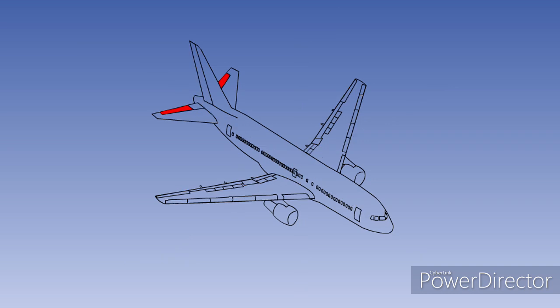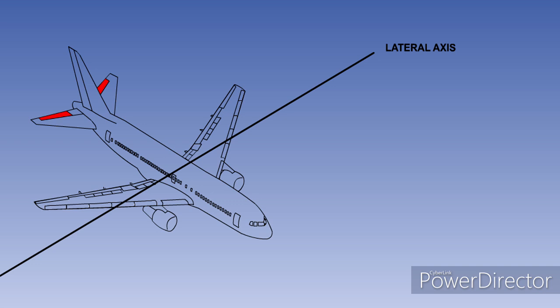In this lesson, we will discuss the primary flight controls which control and balance the aircraft in pitch. Longitudinal control is achieved by the use of elevators, which are flap-type controls normally fitted to the trailing edge of the tailplane or stabilizer. These surfaces control the aircraft in pitch about the lateral axis. The controls must be adequate to balance the aircraft throughout its speed range, at all permitted centre of gravity positions and configurations, and to give an adequate rate of pitch for manoeuvres.